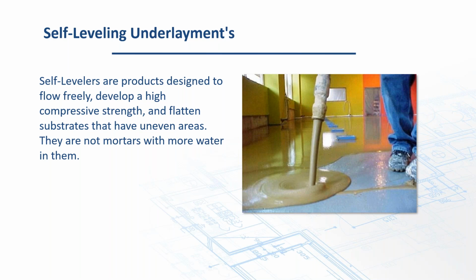But I will tell you one thing about self-levelers that I think is commonly misunderstood. A couple things. Number one, they are a very technical mortar. What I mean by that is most of them have a large variety of chemicals in them. I'm talking up to 20, where a thin set might have 5 or 6. We're talking 20 plus chemicals inside these materials. You do not want to overwater a self-leveler, as an example, because the material that makes it viscous or thin and then sets or gels, you don't want to disperse that too far. It'll take forever for it to set up. They're very technically formulated. So follow the directions, follow the water ratio.